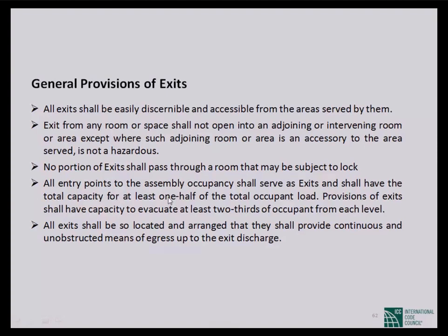All entry points to the assembly occupancy shall be served as exits and shall have a total capacity for at least one half the total occupant load. So you have to be careful about this exit. Every exit should have that capacity, so that half of the population can pass through any exit.